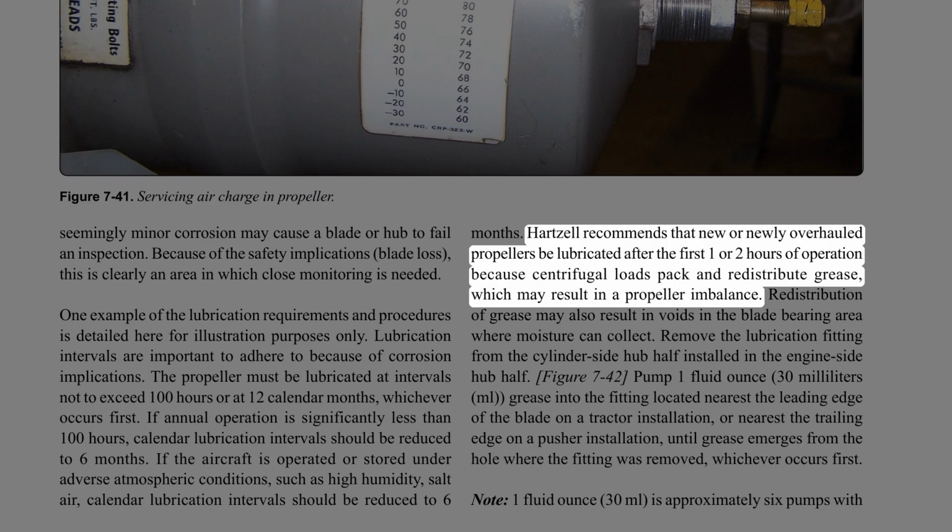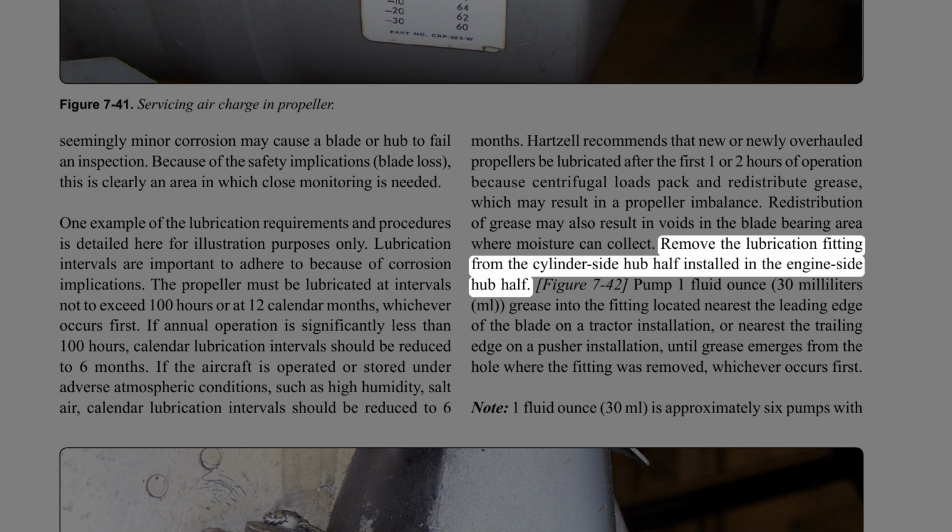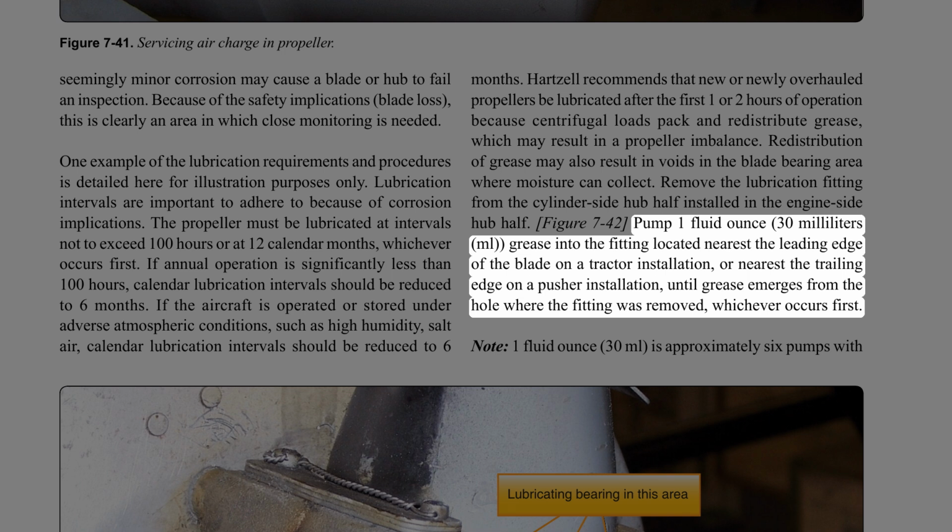Hartzell recommends that new or newly overhauled propellers be lubricated after the first 1 or 2 hours of operation because centrifugal loads pack and redistribute grease, which may result in a propeller imbalance. Redistribution of grease may also result in voids in the blade bearing area where moisture can collect. Remove the lubrication fitting from the cylinder side hub half installed in the engine side hub half. Pump 1 fluid ounce, 30 ml, grease into the fitting located nearest the leading edge of the blade on a tractor installation, or nearest the trailing edge on a pusher installation, until grease emerges from the hole where the fitting was removed, whichever occurs first.